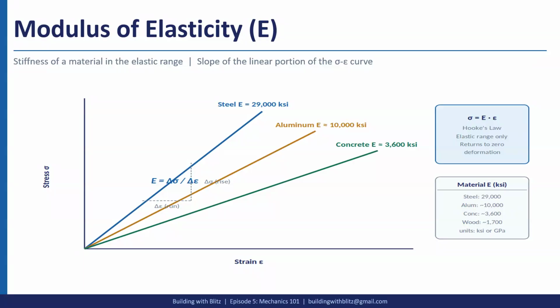So modulus of elasticity, again, very, very important. You really just want to almost memorize these values, but just know that it's derived from Hooke's law, which is the stress divided by the strain gives you the modulus of elasticity for the elastic region.